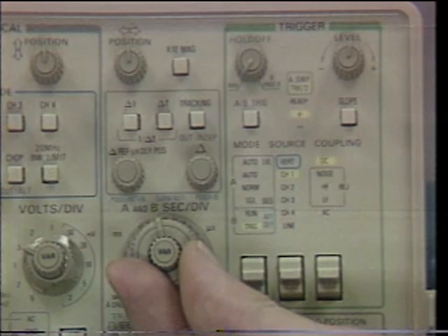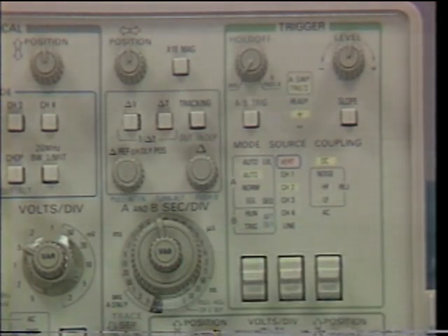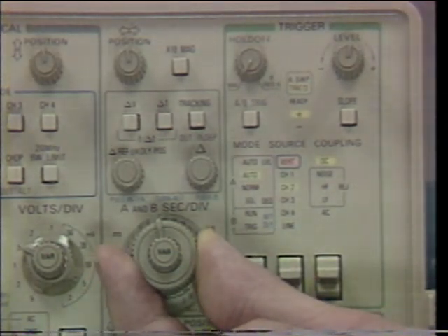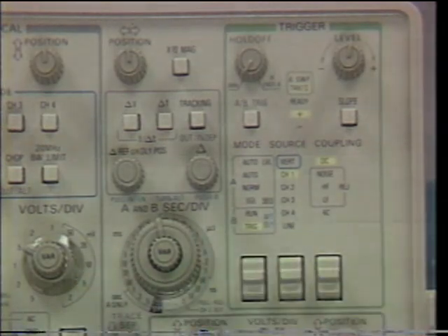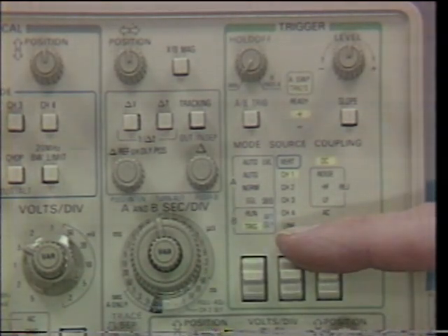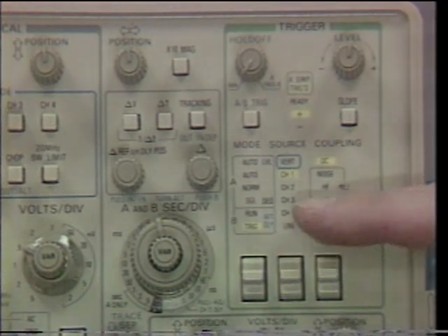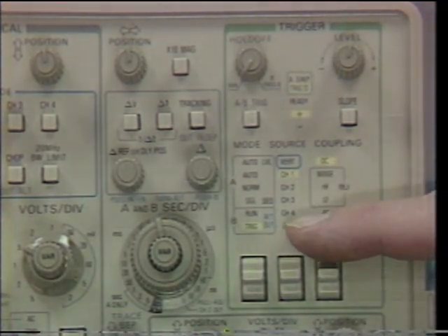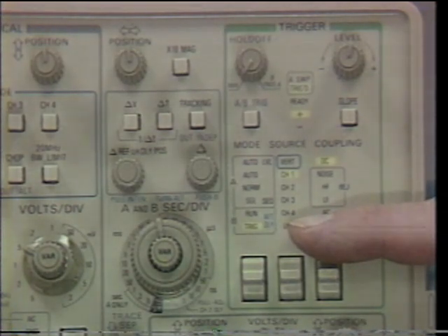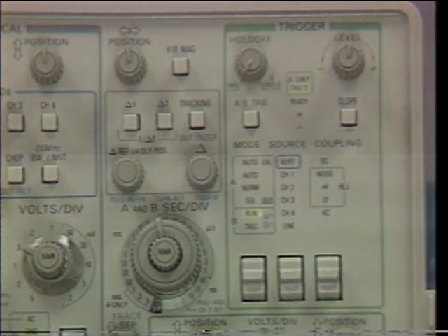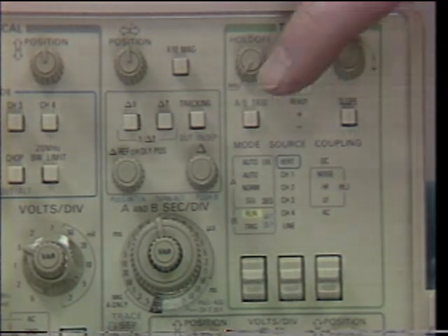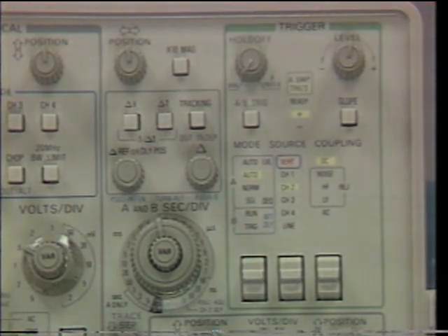Now when we lock the knobs together, the display of the A trigger status is automatically selected. Now there's another case in which we pull the second per division knob. If the B mode was trigger after delay, the LEDs immediately show us what the B trigger status is so that we are alerted to the requirement for B triggers. Of course, we can change the mode to run after delay if we like, and if we prefer to operate on the A trigger even though the B sweep is displayed, we simply push the AB trig button.